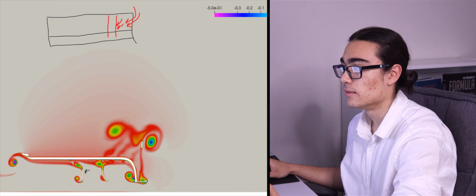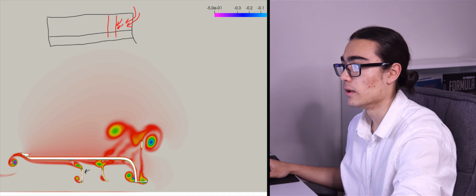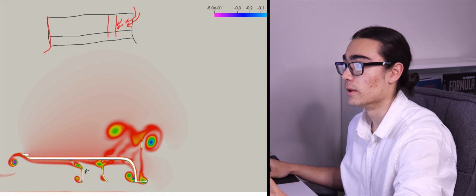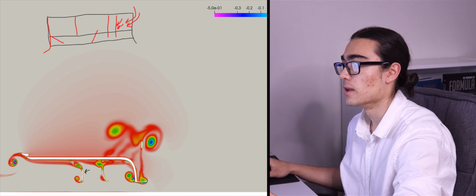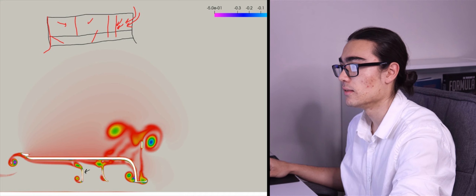Now let's consider the other side. Let's say that we're in a wing where it's not as close to the ground, for example, and we've got not as low a coefficient of pressure underneath, or we're in a section of wing where maybe the outside section is backed off, maybe the inside section is backed off, and we're right in the middle, then we're going to have less flow coming from the outside and less flow coming from the inside.